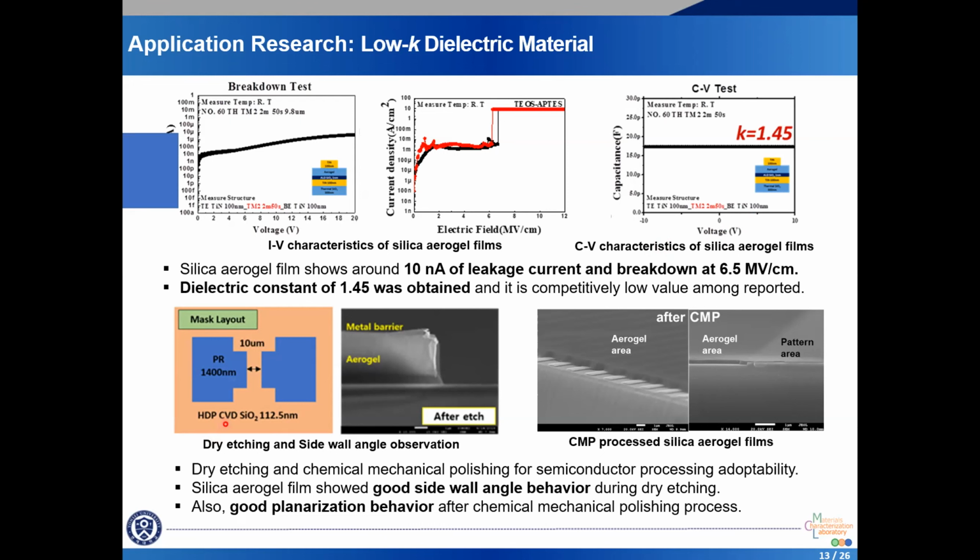Furthermore, semiconductor processing adaptability was proved. As you can see, the silica aerogel film showed a good sidewall angle behavior during the dry etching step, and also a good planarization behavior after the chemical mechanical polishing process.